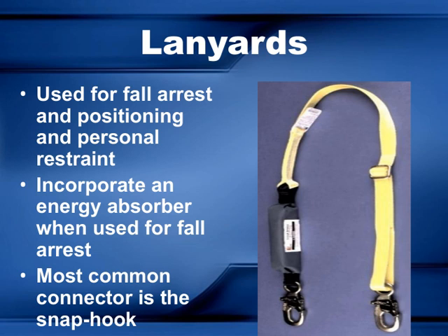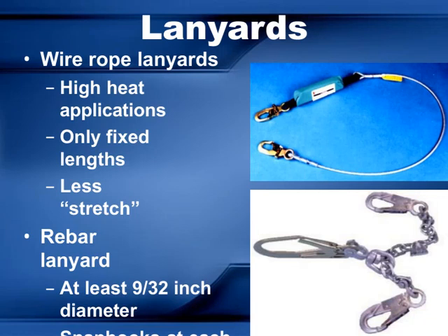Remember, choosing the right lanyard and inspecting it regularly is crucial for maintaining a safe working environment. Let's talk about wire rope lanyards today. These are specially designed for high heat applications, which means they can withstand very hot environments without losing their strength. One key point is that they come in only fixed lengths, so you need to select the right size for your specific task.